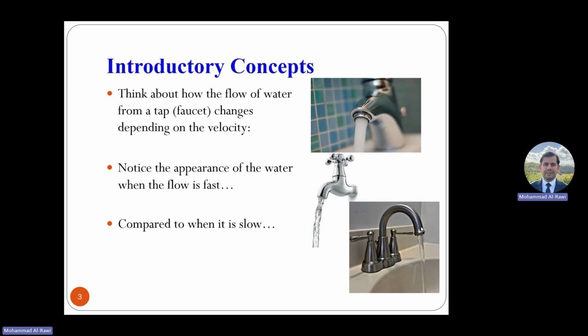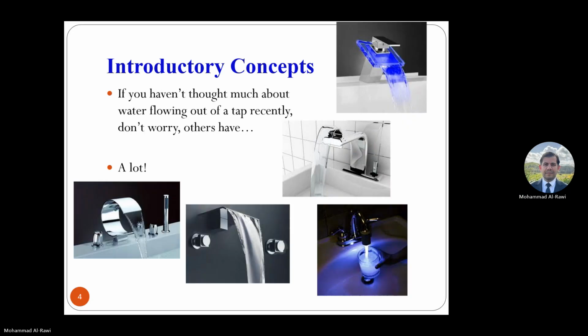However, if you open the tap just slightly, with a low flow of water going through it, you can see through the water, and that shows the flow is laminar, not disturbed, and you can distinguish between the two flow regimes. And between them, where it goes from laminar to turbulent, is the transitional area.